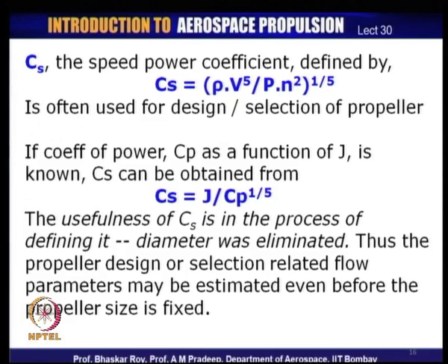As a result you can create a propeller characteristics conceptually without, to begin with, bothering a priori about the size of the propeller, which can be factored in a little later in the design process. So, this speed power coefficient allows you to create a conceptual propeller without fixing the size right away, and the fixing of the size can be slightly deferred to a later date.